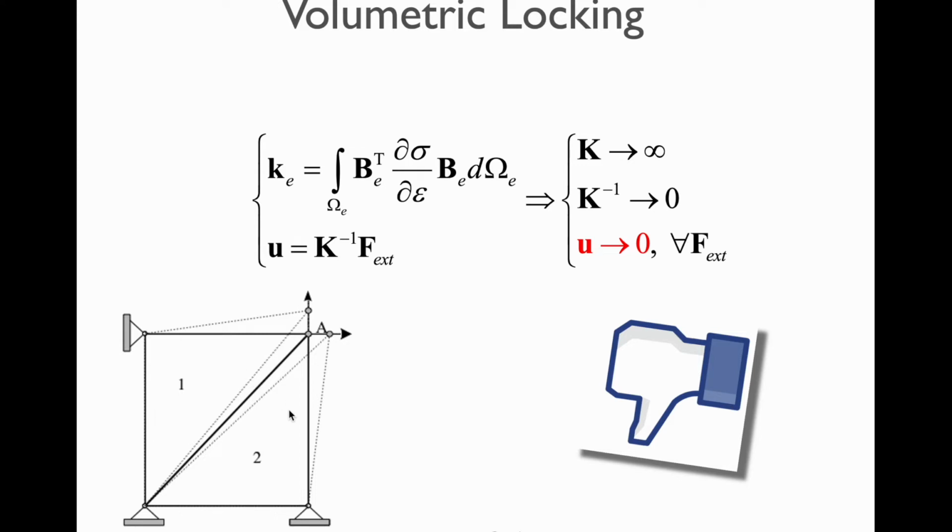So we are violating the constant area, or incompressibility, in this case. It's more visual here and more mathematical here. But anyway, incompressibility forces the locking, and locking is when stiffness goes to infinite and displacement goes to 0.